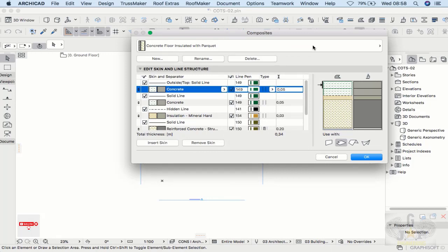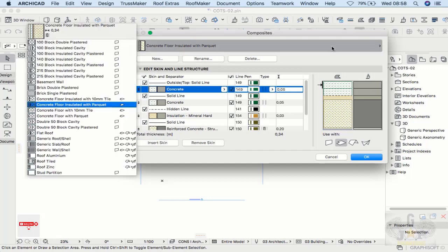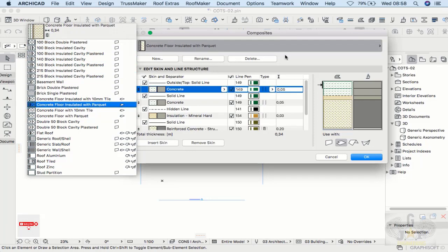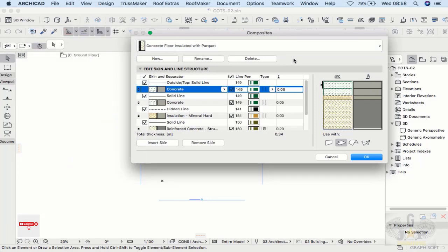Before coming to your composites, it's vice versa. The good part is that ArchiCAD has already preset specific composite elements. It's just up to you. You can tweak them, copy, duplicate them the way I showed you, or if you want something more specific and vivid, you can go to building material and create a new type of material, which is what we're going to do.